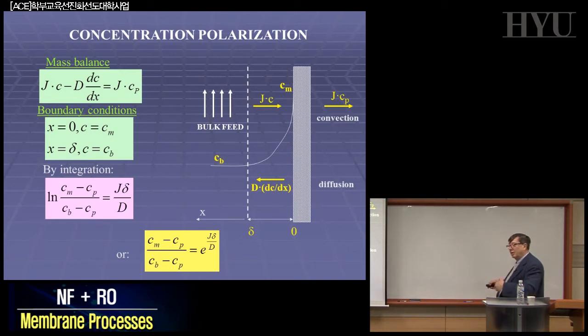You are creating mechanical mixing in the system in such a way that it's not just back diffusion, Fick's law, controlling the removal of the salts, but a significant turbulence that you can create. I was mentioning here, you can work with a velocity of 5 meters per second, very, very fast, with a Reynolds number that can be 20,000, 25,000. Otherwise, the system does not work.